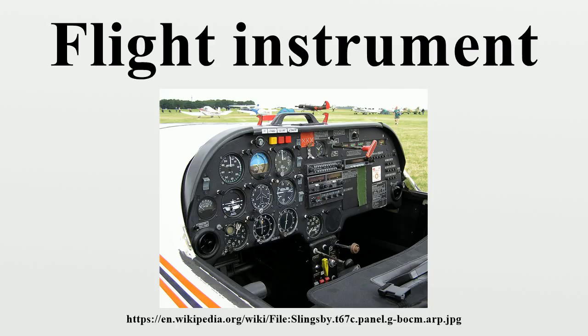Visual flight rules require an airspeed indicator, an altimeter, and a compass or other suitable magnetic direction indicator. Instrument flight rules additionally require a gyroscopic pitch bank, direction and rate of turn indicator, plus a slip skid indicator, adjustable altimeter, and a clock. Flight into instrument meteorological conditions requires radio navigation instruments for precise takeoffs and landings.